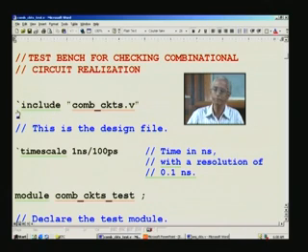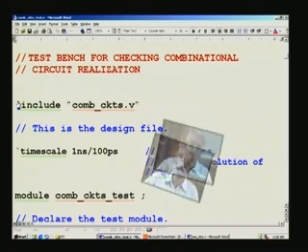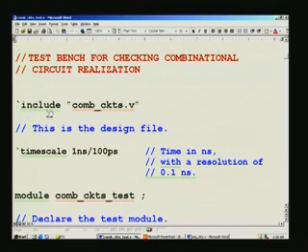This is the very same thing as a C command instruction. We have a tick here, a reverse tick, and this is a must; this is a keyword that you cannot ignore. Separate it with one or more blanks or tabs, and then put the file name within quotes. These quotes are also required, and note that it is a .v, so you have to completely specify the file name.